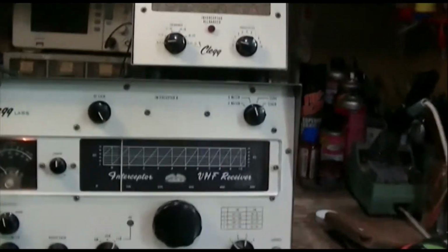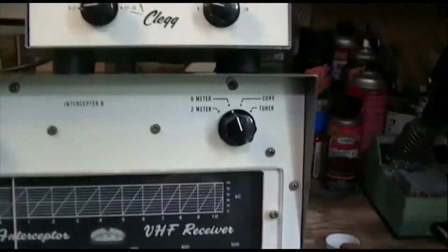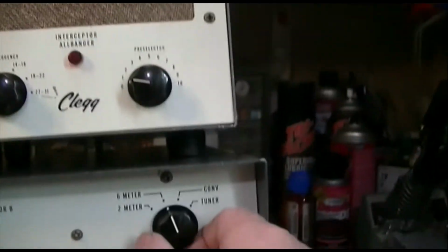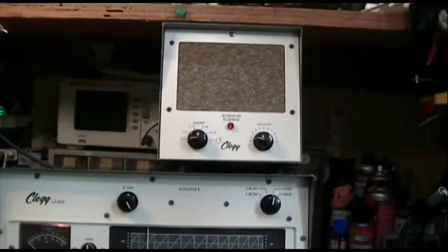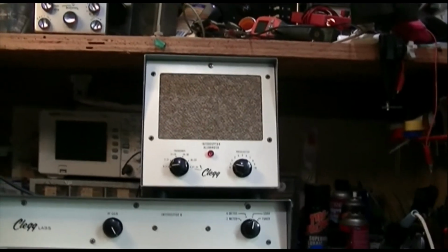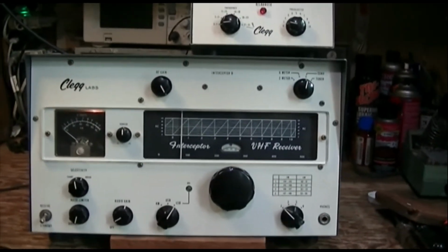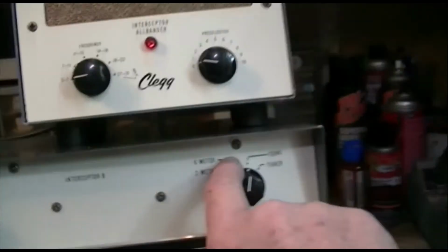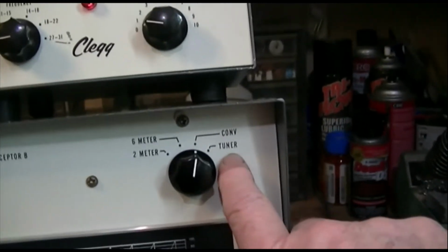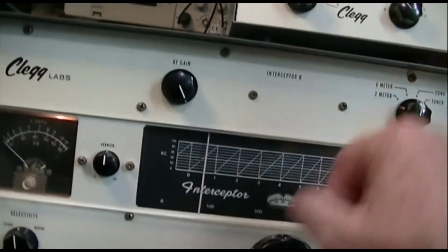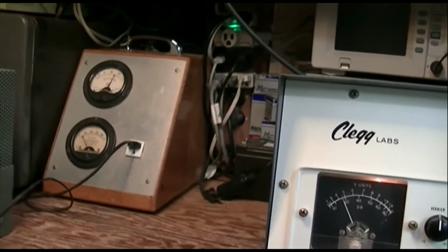So first thing you do, I've got this thing hooked up in the back. Just go over here and select converter, and watch what happens. It turns itself on because it's getting its V plus and its filament voltage from this receiver, from the accessory jack in the back. And then this is selecting the receiver input here, 2 meters, 6 meters, in this case is converter, or if we had some other optional tuner outboard, we could use that, but we're going to use this. So we'll select 40 meters and turn it on, give a listen.